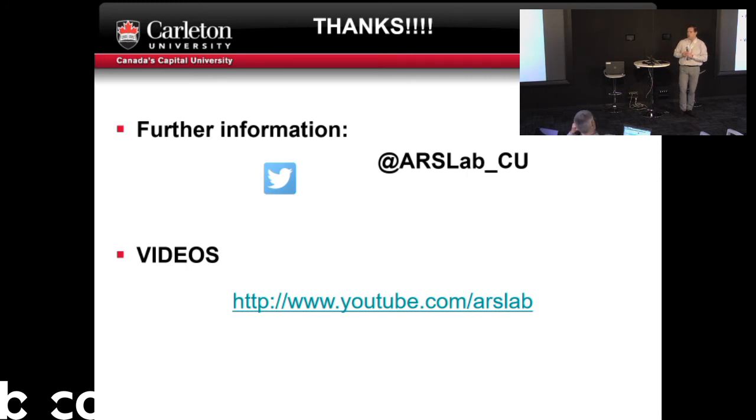I didn't say a word about the simulator and how this is simulated. But the HLA provides an API to hook up your simulator. So your simulator should be adapted to HLA and provide input-output ports, let's call them, to talk to the HLA. And then you can make simulator A talk to simulator B. But they don't understand each other at the semantic level. They might understand the bits that are transferred from one simulator to the other, but what the model means is not understandable. And that's where the main problem is.